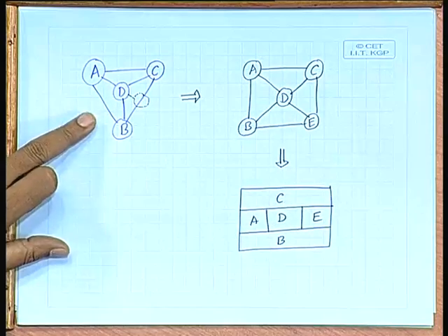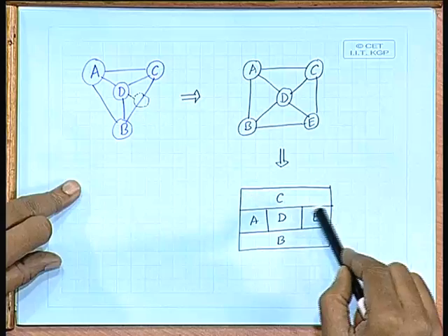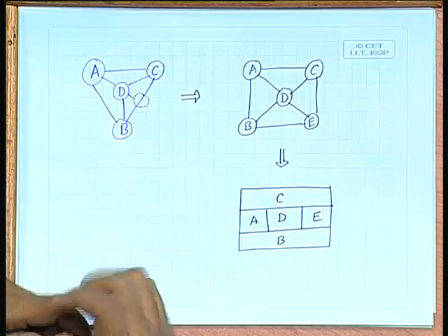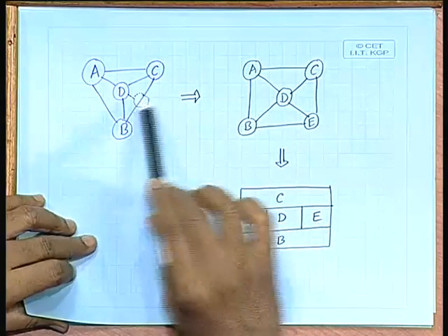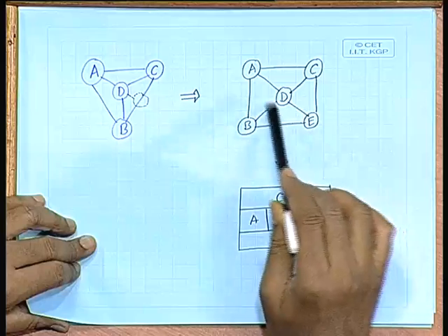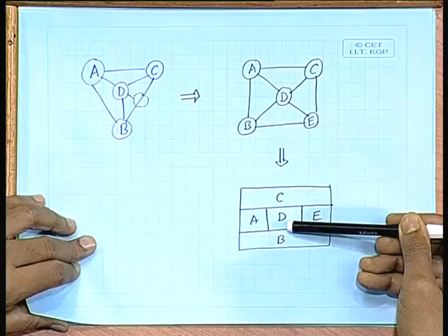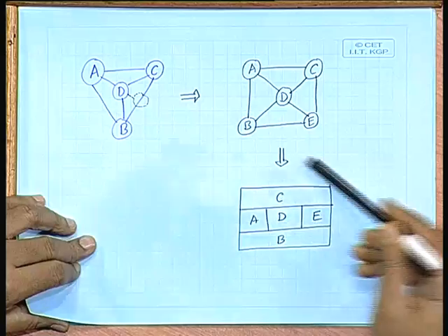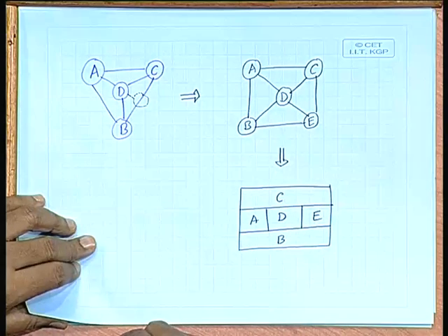This E is actually a dummy one, it does not carry any meaning, but you can merge it finally; there will be a blank space. By introducing this, you can have a properly triangulated graph for which the dual exists, meaning you can get a floor plan. If you do not do this, you cannot get a floor plan from it.